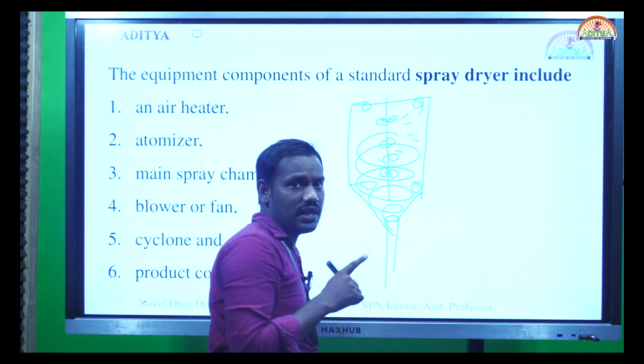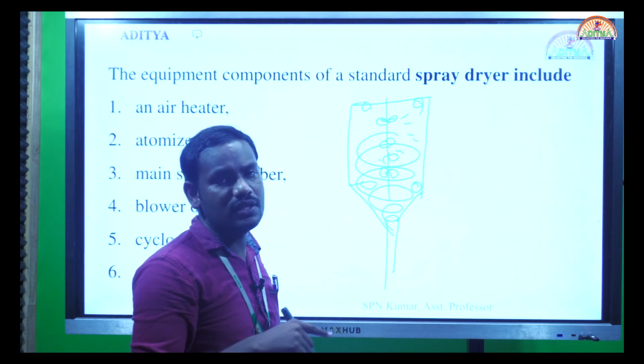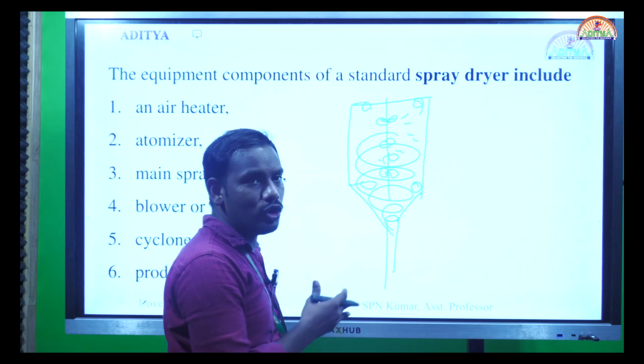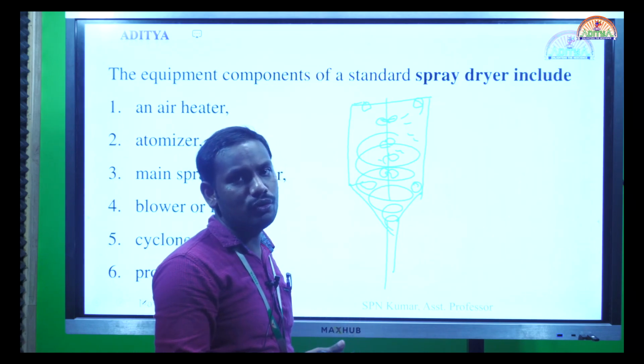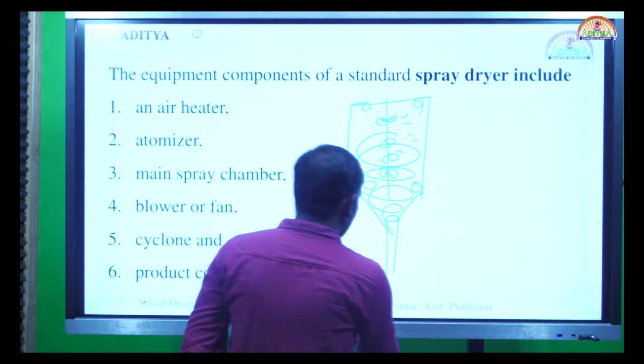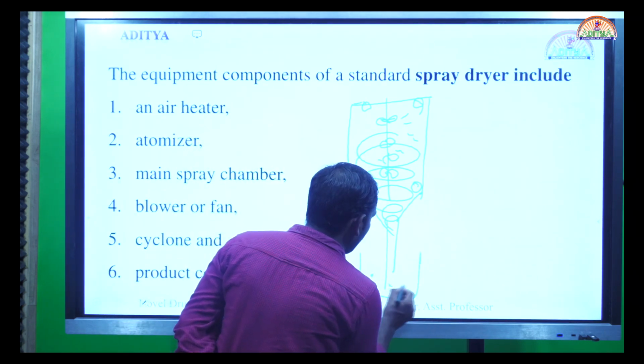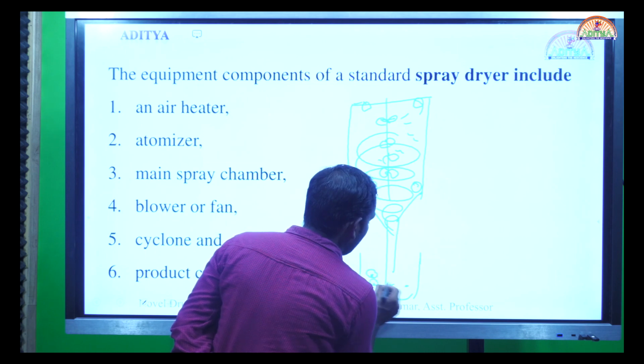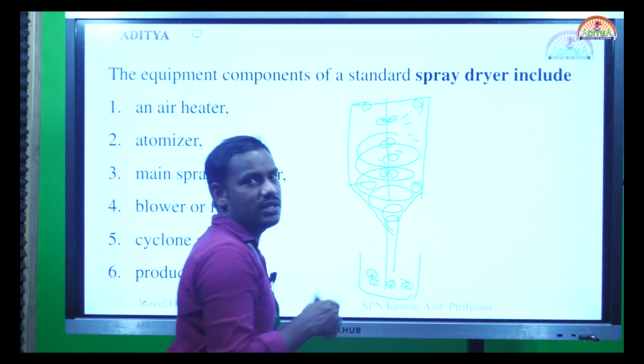During this rotation of the core bed, powder bed, these nozzles will spray the coating solution. So air is being circulated, the powder bed is moving in the air, and your coating solution is sprayed onto that core material, your solid material. So finally at the end you are going to get microcapsules which are surrounded by the coating material. So that is spray drying.